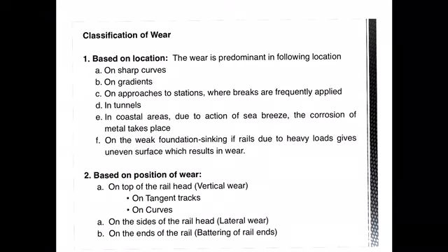And also, whenever the track is laid on a weak foundation, sinking of rails can occur due to the heavy loads, which gives an uneven surface, which will result in the wear. Okay, so these are some of the places where the rail wear is predominant.